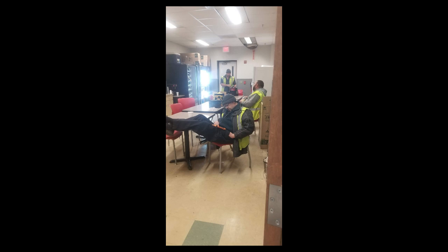41. How is the cabin pressure of an aircraft maintained in flight? By controlling the rate of the air flowing out of the cabin. 42. Which oxygen system employs a regulator that operates only when the user inhales? Demand flow system. 43. If oxygen bottle pressure is allowed to drop below a specified minimum, it may cause moisture to collect in the bottle. 44. What is the purpose of pressurizing the aircraft cabin? C. To make human flight possible in the hostile environment of the upper atmosphere.